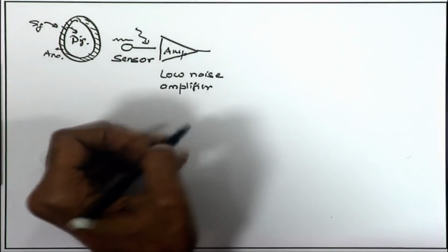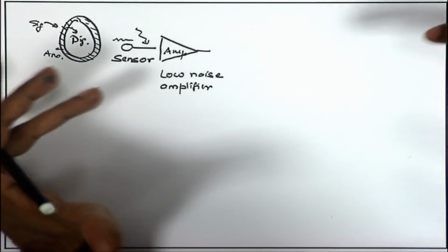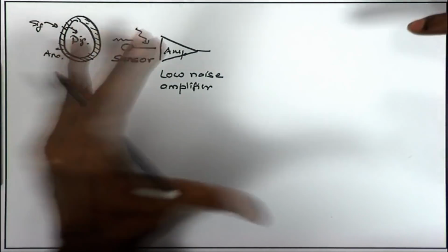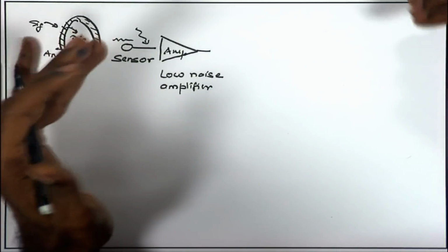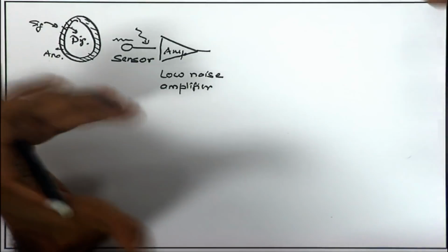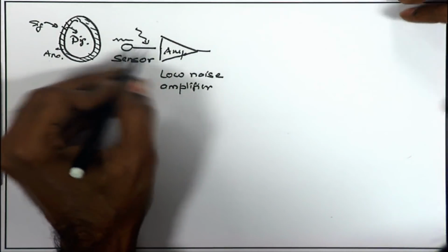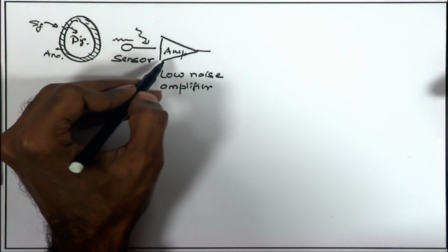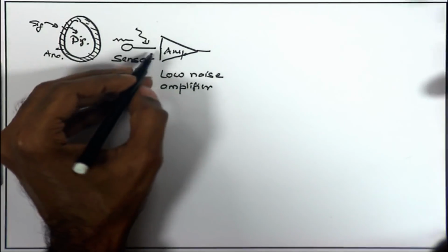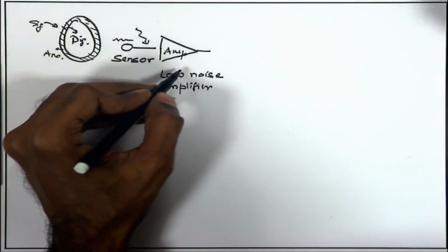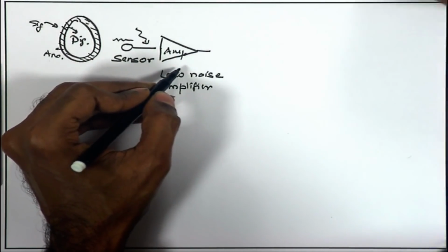Although this term of low noise amplifier is kind of reserved for RFIC low noise amplifier or LNA, where we have to deal with high frequency operation, matching consideration. But in general, in analog design also, whenever we are facing the analog signal or sensor to the mixed signal IC, the first stage happens to be the low noise amplifier, where apart from amplifying the signal, the amplifier must make sure that it is not corrupting the signal by added noise.